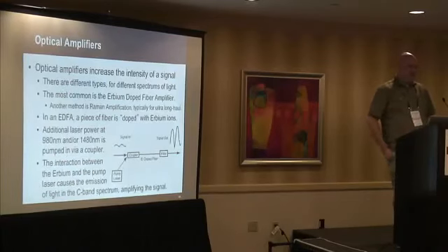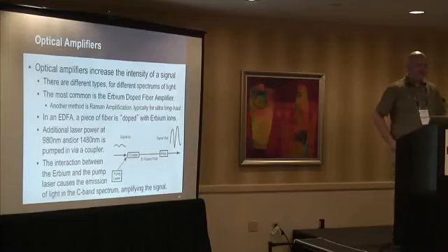Optical amplifiers let you increase the intensity of the signal. There's a bunch of different types. It depends on the frequencies of light. Different physics are required. The most common thing that most people deal with is an EDFA, an erbium-doped fiber amplifier. What that means is a piece of fiber that's doped with erbium, and by injecting a laser of a completely different frequency, you can cause the stimulation of light, and in these other frequencies, you can make the light get brighter. So you have a pump laser across this fiber, and it causes the light to get excited and amplify.